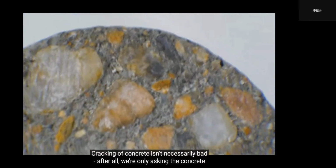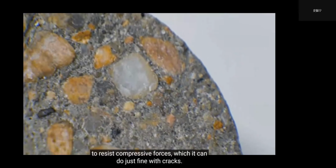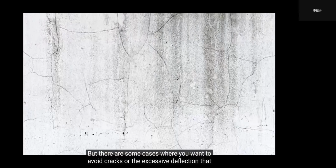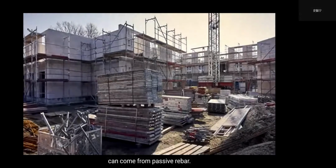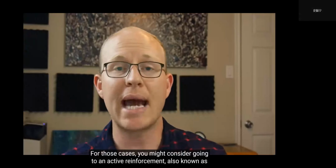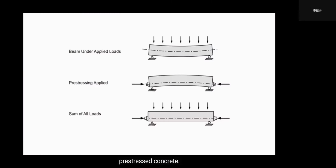After all, we're only asking the concrete to resist compressive forces, which it can do just fine with cracks. But there are some cases where you want to avoid cracks, or the excessive deflection that can come from passive rebar. For those cases, you might consider going to an active reinforcement, also known as pre-stressed concrete.